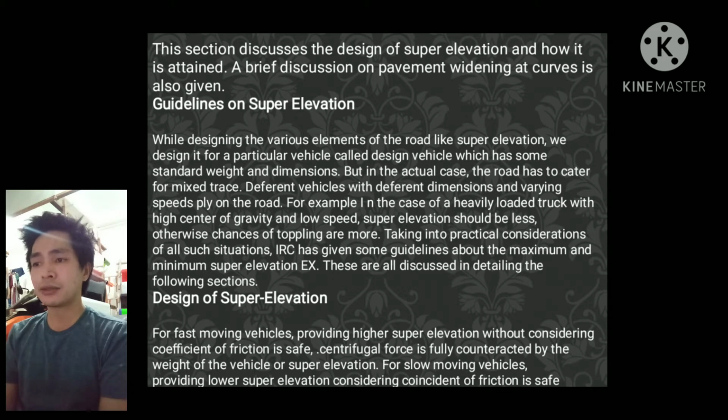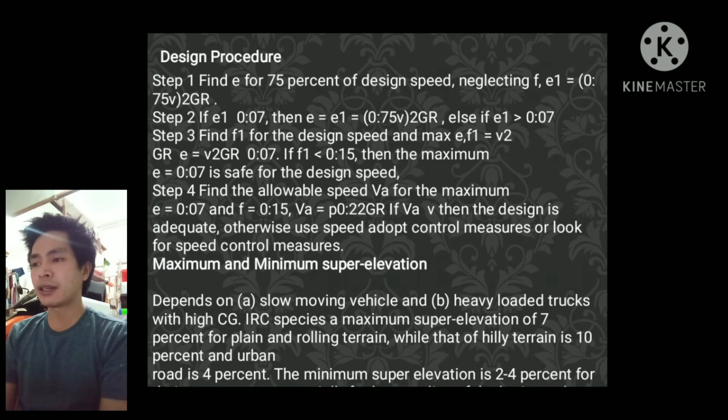Centrifugal force is fully counteracted by the weight of the vehicle or super elevation. For slow-moving vehicles, providing lower super elevation considering the coefficient of friction is safe. Centrifugal force is counteracted by super elevation and coefficient of friction.